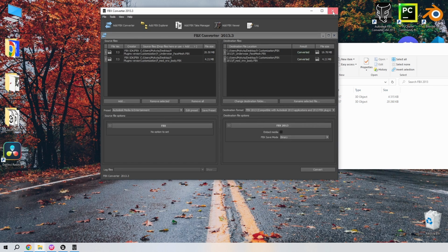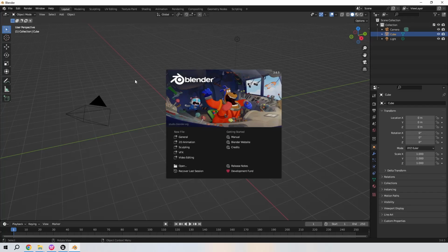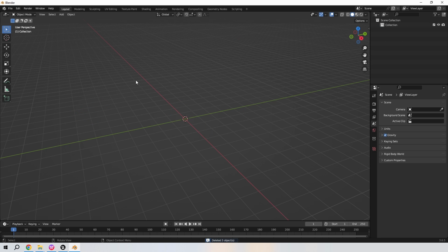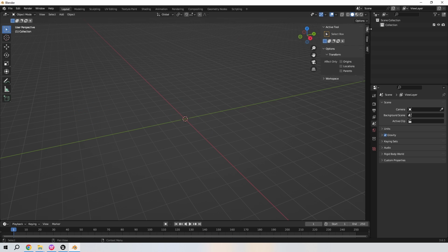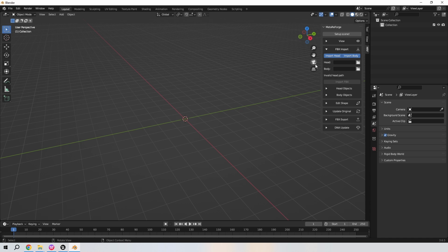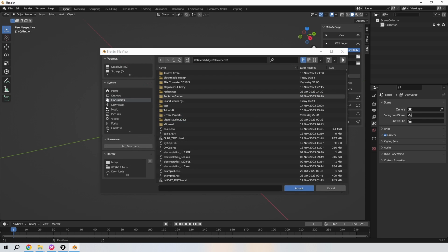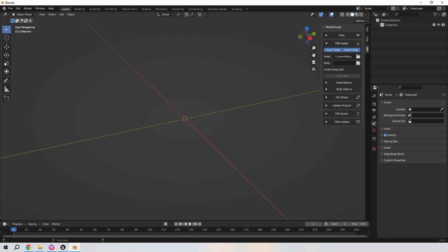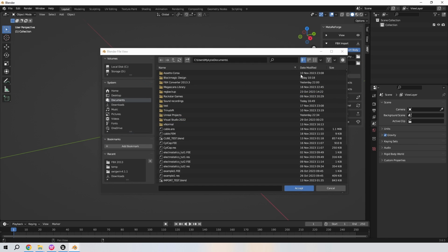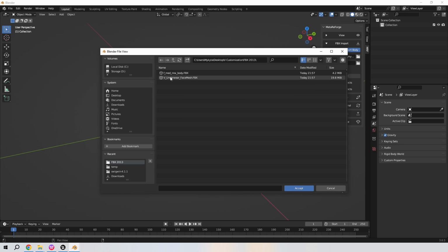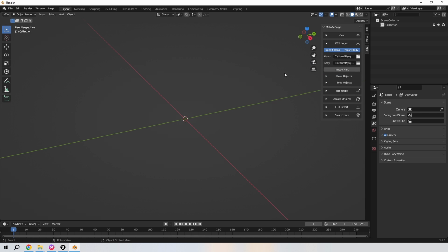Now let's go to Blender, clear the scene, open End Panel, MRF, click here to set scene units compatible with Unreal Engine, set path to head FBX, to body FBX. If you want to edit one mesh only, you can disable head or disable body, but I will show you both.